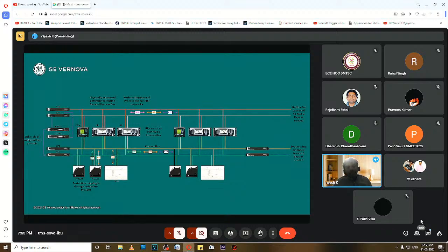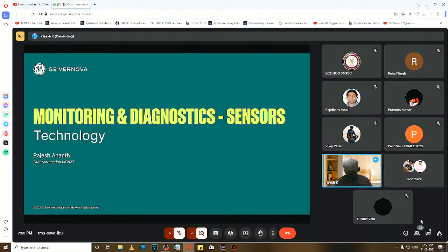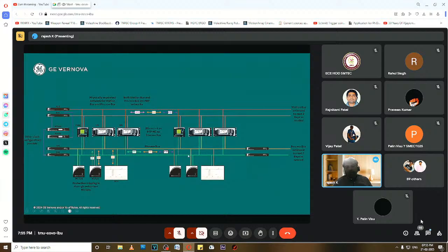So now you can think, after doing this, how my substation network will look. Instead of having hundreds of wires, you will have only a couple of fibers coming to the device. You can imagine this white one like an SCU, or a protection device in the middle, which has two fiber optic links, one from the bottom and one from the top. The one from the bottom is the process bus. The process bus carries the sampled values which come from the non-conventional instrument transformers and the sensors.